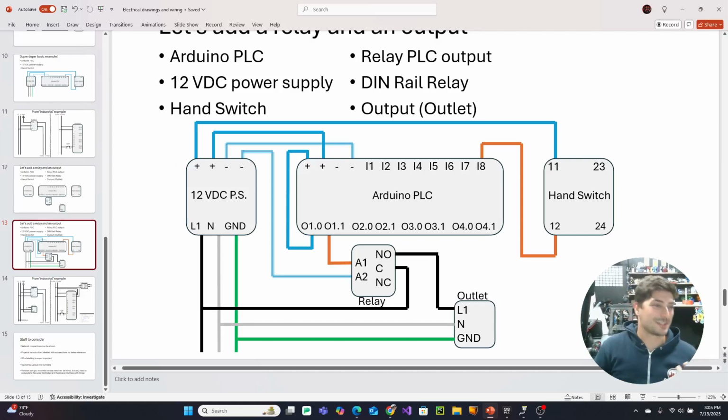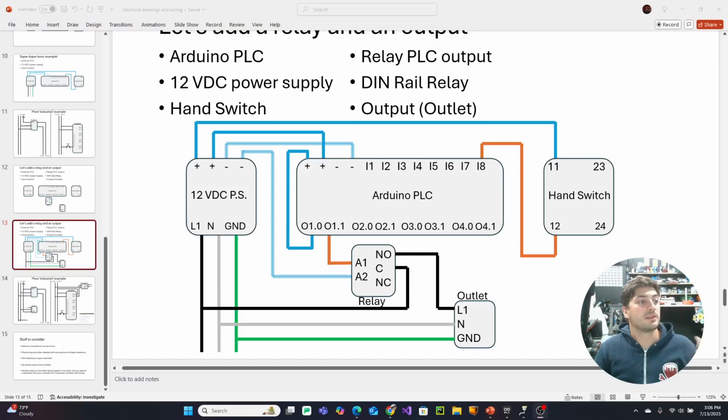Let's just take a look at this practical example, okay? So when the PLC energizes that wire, this relay connects the common to the normally open channel. And then when the coil releases, the common is connected to the normally closed channel. That's a super important concept, not just for relays, but for all of electronics. So if you look up relays and common, normally open, and normally closed, you'll learn a lot about